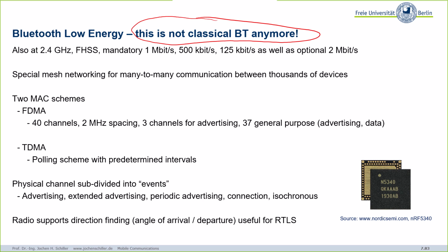But what is more important is, look at the channels. It's not 79 anymore, it's 40 channels, with completely different spacing of the channels. And we have 3 specialized channels for advertising and 37 general purpose channels. So you see that that is a different physical layer. So it's not compatible. No way.